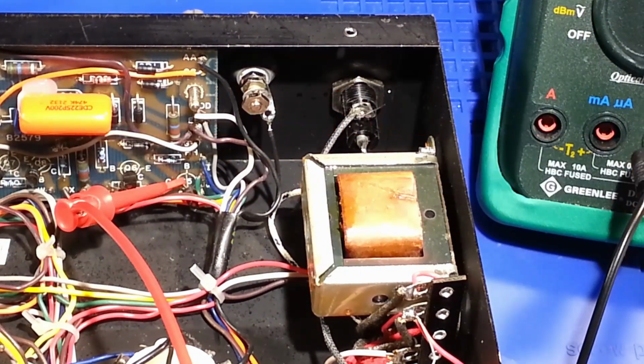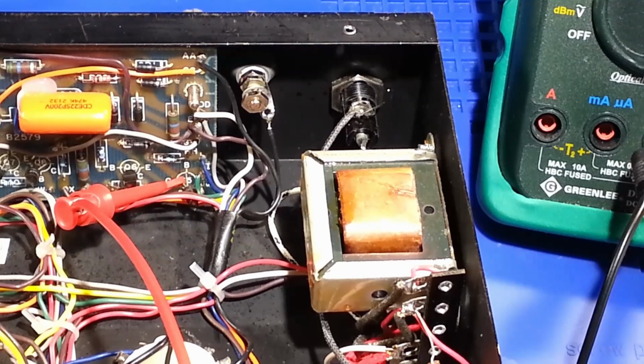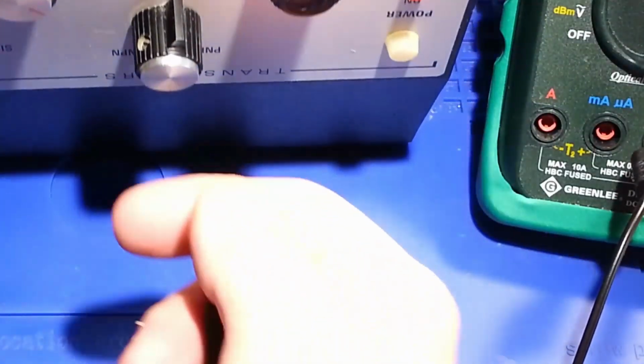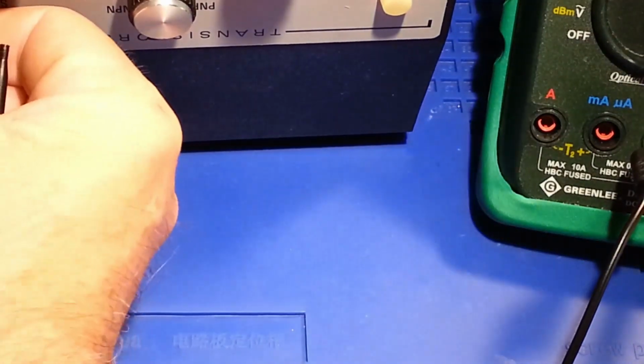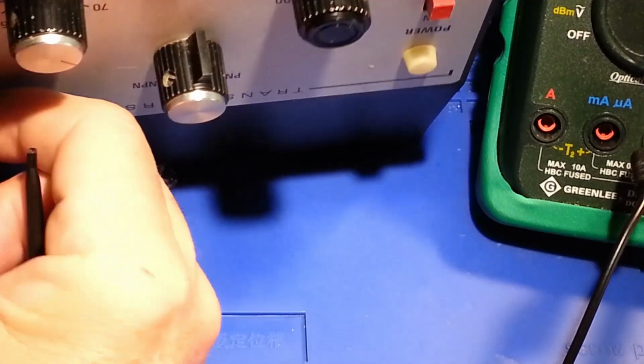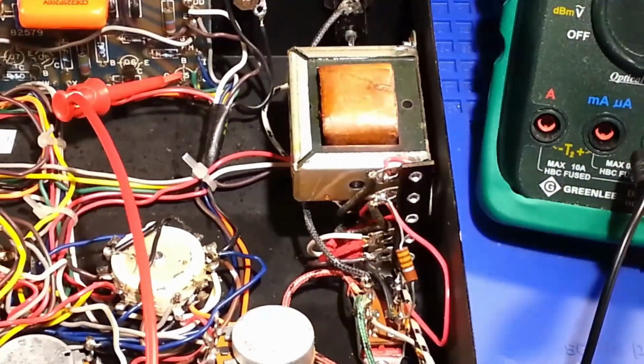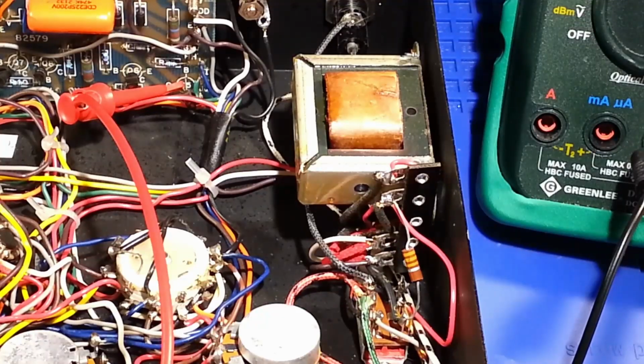if we switch this to power, signals in that switch position, and the switch is over here, power is in that one. If we switch that to power on an NPN, that collector should go through to the base of Q7 through a 5.6 kilo ohm resistor.